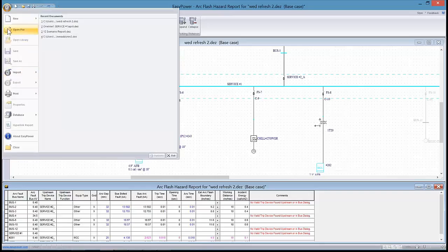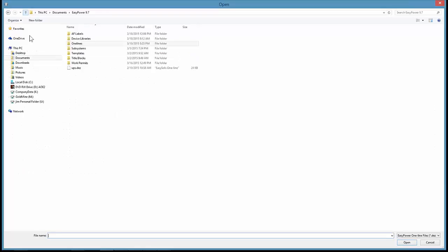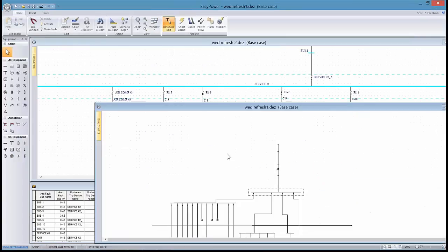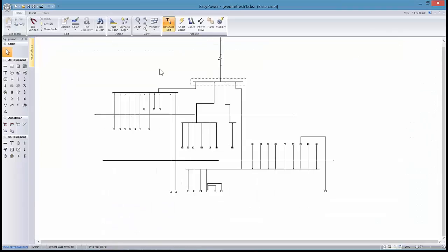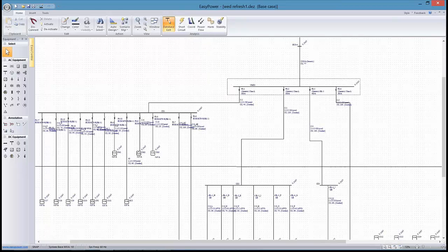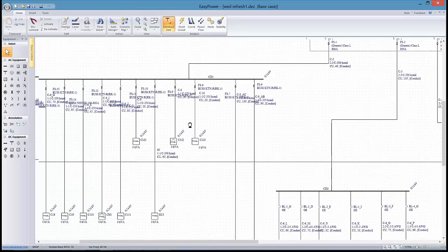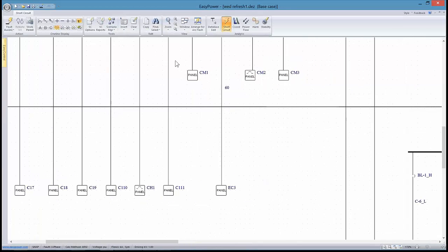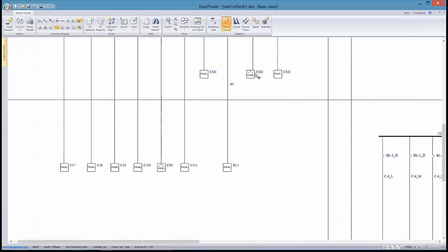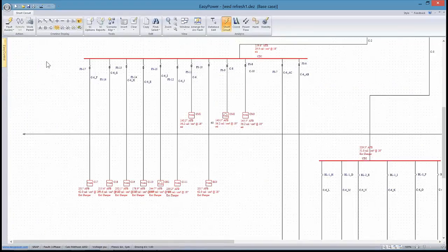Let's jump into a little bit more advanced question on sequence of events. Okay, same kind of a situation. Essentially, a first-time user of OneLine, nothing necessarily at odds with what's going on. As we enter short circuit, we don't get an error report, which is a good sign. We go ahead and fault the buses, and we see that we have a lot of relatively high incident energy.